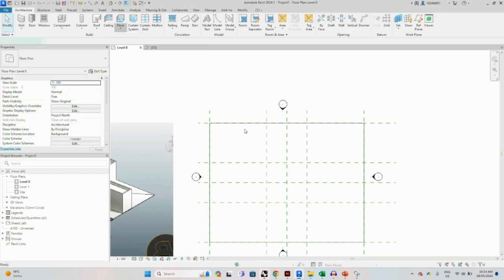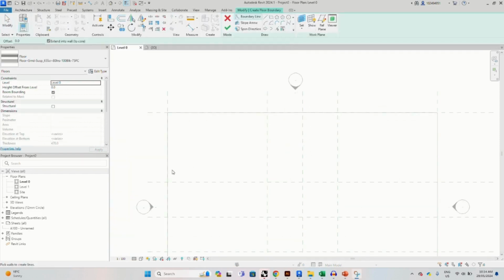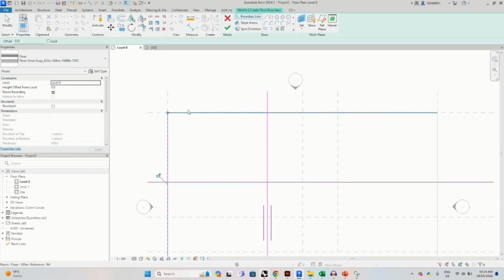So in order to do that, I'm just going to use floors again, and I still can't use the rectangular tool, so pick line should do the job, and trim extend to trim it, TR for shortcut again, and that's the tool in the tab.